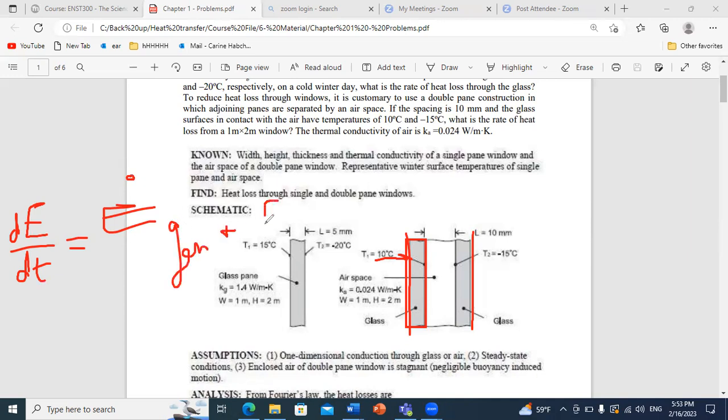This is the general energy balance that you can put for any system. Now you should look at your terms. What do you have here for this layer? You don't have any generation, so this term is 0. You don't have any transient variation, so this term is also 0. You only have fluxes of energy that can come in and others that can go out.